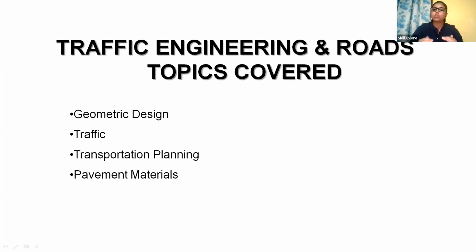And here we'll be giving only the general glimpse of that area, which pavement materials are used for constructing a pavement, and what are the layers of pavement. Flexible pavement will not be the same as rigid pavement, like the layers will be different. For a flexible pavement, the top surface will be covered with bitumen, and for a concrete pavement, it will be different. So what are the layers, like subgrade, subbase, base, and the surface course, all these things will be covered under pavement materials.